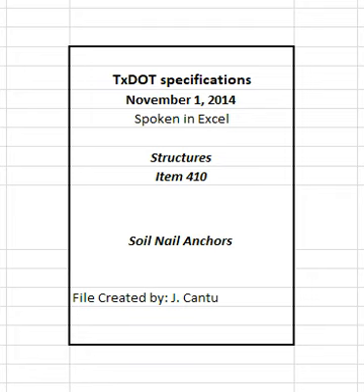4. Construction. 4.1 Soil nail wall construction plan. Submit a soil nail wall construction plan at least 30 days before beginning construction. Begin soil nail wall construction once the construction plan submittal is accepted. Provide detailed project-specific information in the soil nail wall construction plan that includes the following: project start date, an overall description, and sequence of soil nail wall construction.